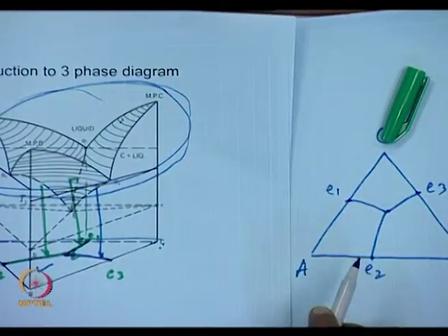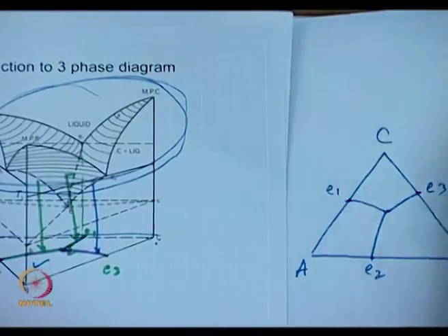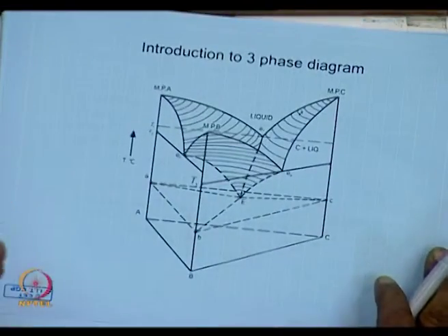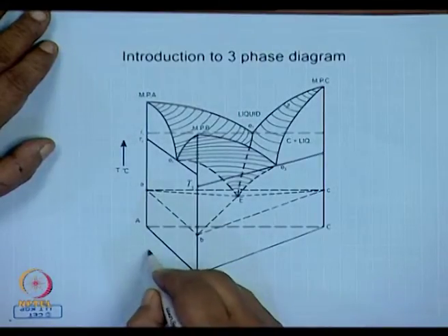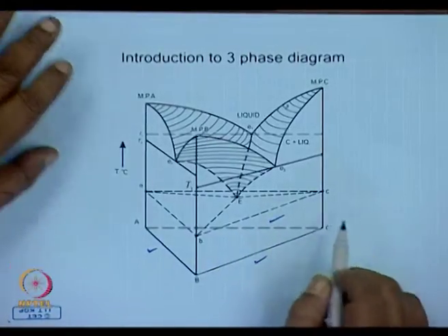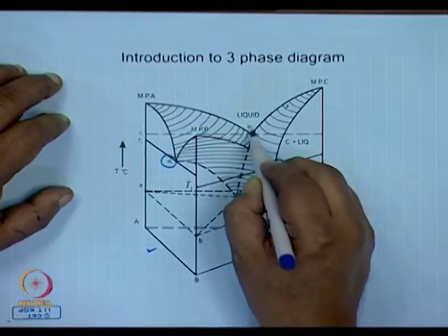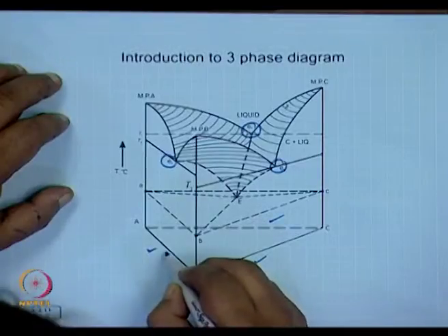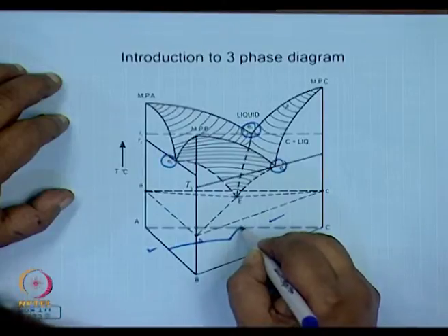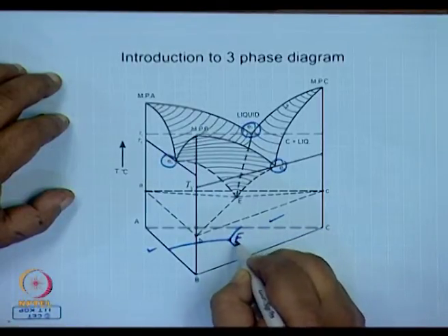And this is the way we start simplifying. So in this particular diagram, I am repeating again because this requires a concept of three dimensions, and you have to imagine a bit: three different phases, three different binary eutectics, they melt together, react together, giving us on the two-dimensional diagram this sort of a joint.